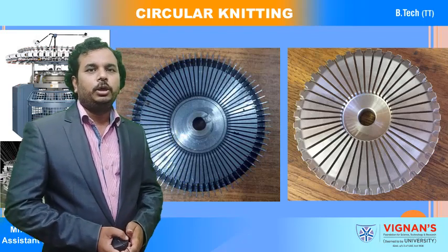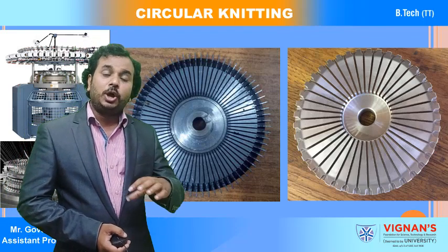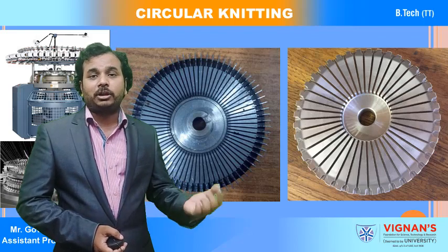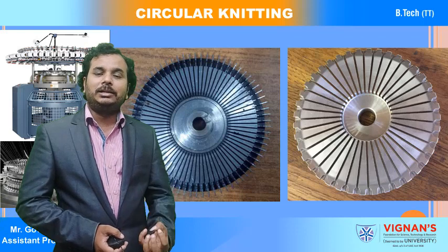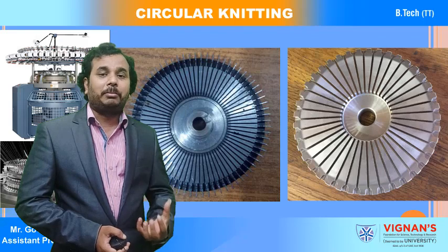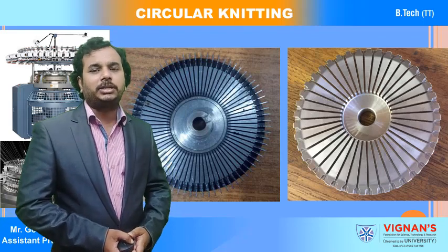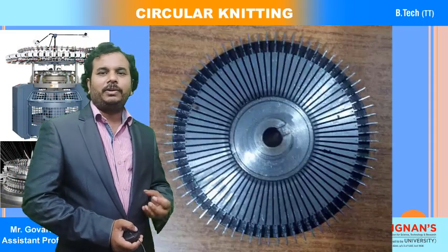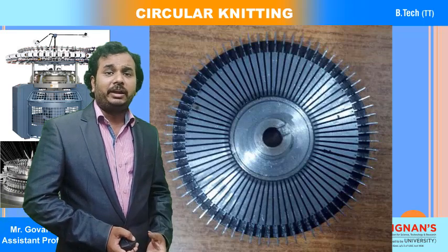So what will happen, we are going to mount the cams on the top of these needle butts, so that during rotation of the dial, the needle butts in the dial are going to follow the particular cam track. So this is how the dial needle beds are available. Now you can observe closely the image of the dial and the needles which are placed in the dial case.